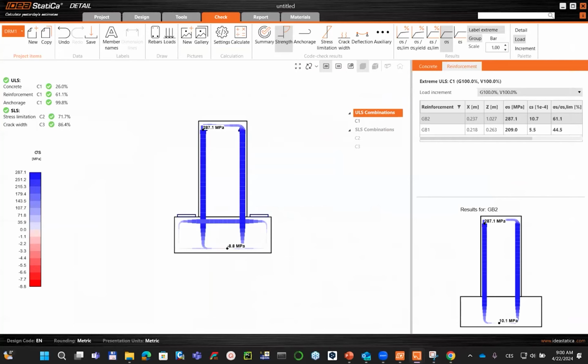And there is a very long question. I can just put it here so everybody can read it. According to Eurocode 1992-1-1, for indirect supports the shear reinforcement in the beam that you calculate in this example must be added to the direct shear reinforcement.